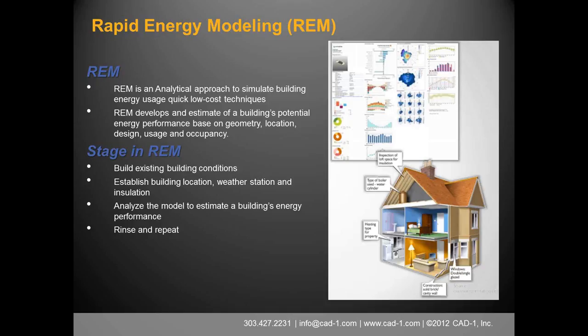A little tongue-in-cheek, but what we mean is that it gives you the ability to do various iterations of a project and look at alternatives, to see which one comes out best for client needs, or which you like best. You're doing this at every stage: schematic design, design development, and CDs. The performance you get back in schematic design will change greatly by the construction document level, when you have the building envelope in there. It becomes a harder number because you have more information built into the model. So it's both the rinse and repeat on your different ideas and the continued progression of the project, and you continually do this rapid energy modeling.